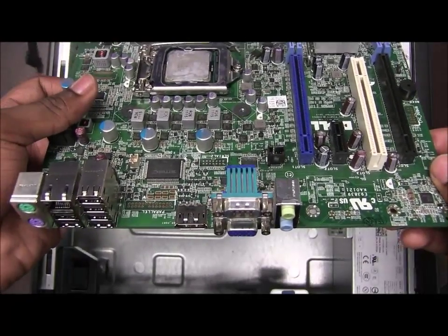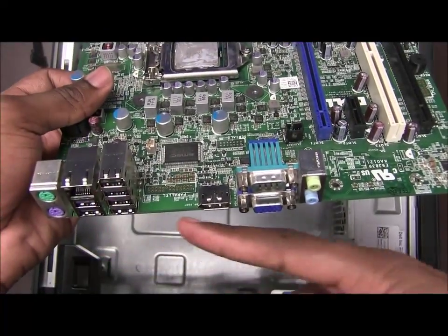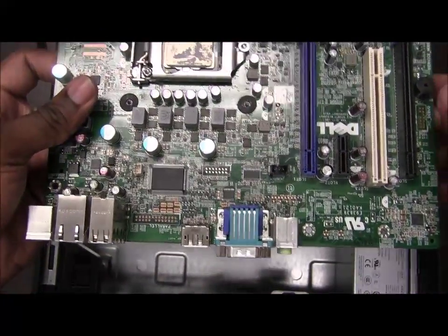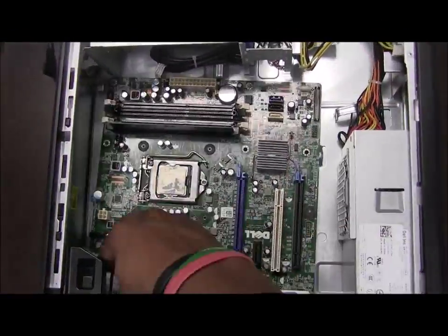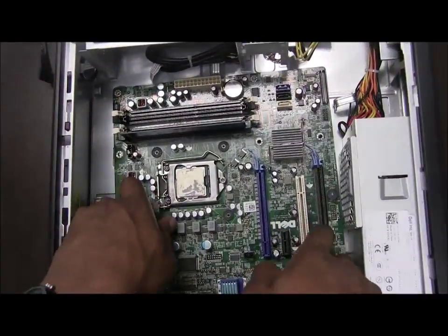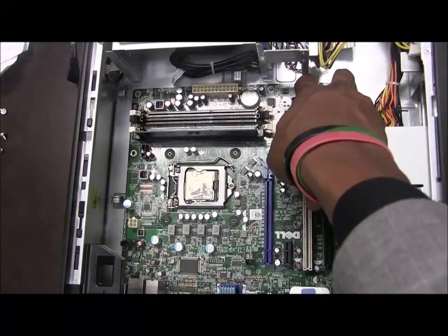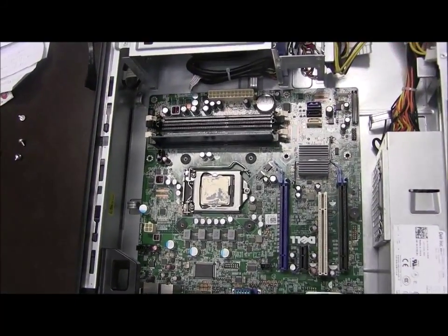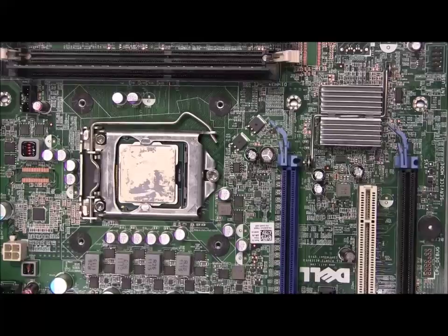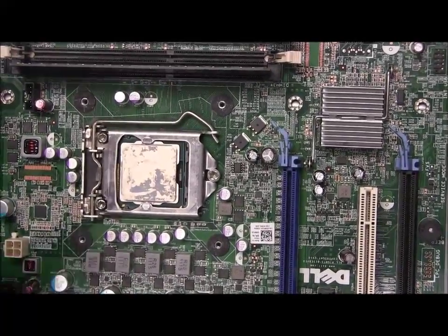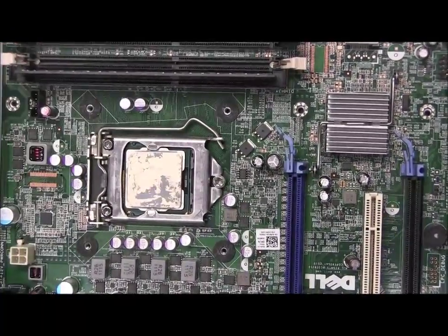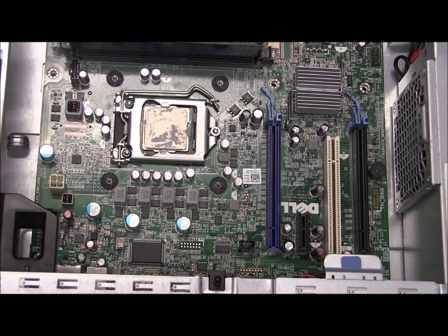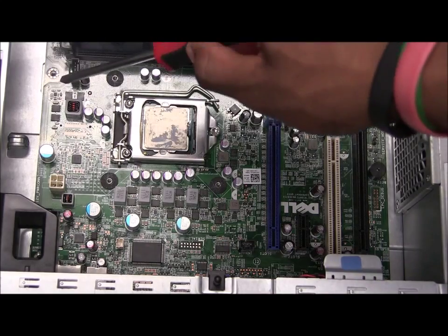To install the motherboard, simply place it in with the back peripheral ports facing the back of the computer. Once you have placed the motherboard into the computer case, you want to make sure the holes in the motherboard match up with the screw holes in the computer case. Once you have done this, you can now screw in the motherboard. There are 8 screw holes located throughout the motherboard that you will need to screw in.